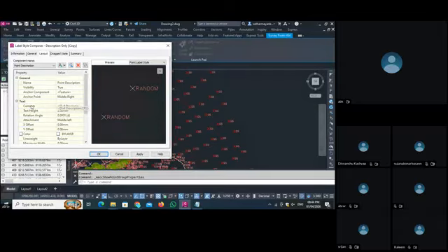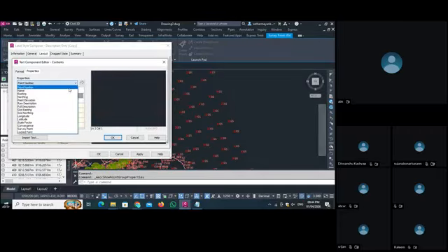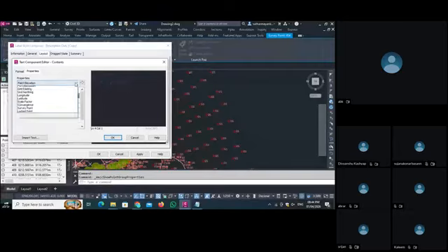So you can go here in the contents. In the content, you click on the three dots. Right now it is set as only the description, but now I want to modify it. I want the description with another thing also. Now I select that I want to show the point elevation also with the description,